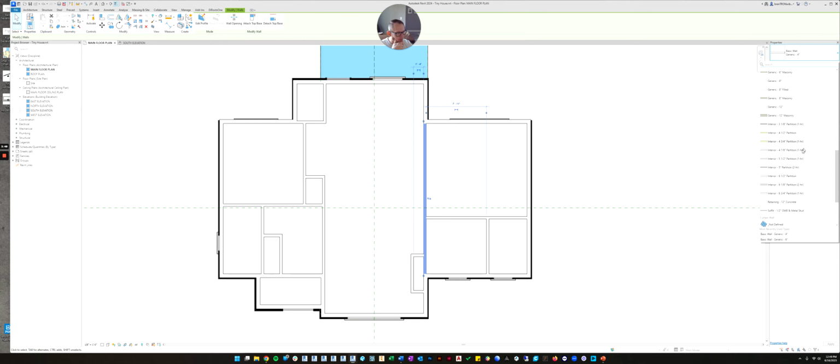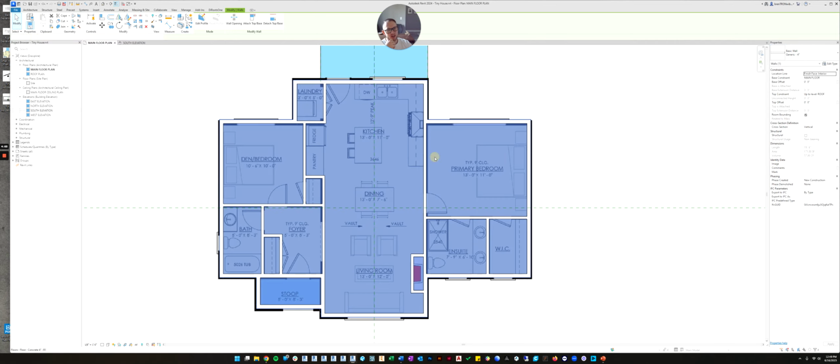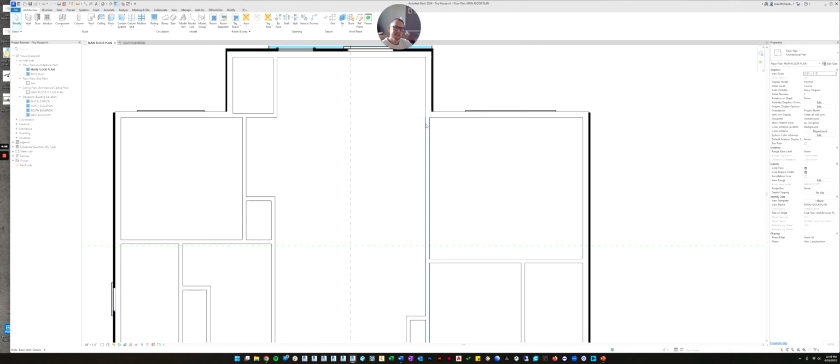Well, I actually do see one that will probably be pretty close. It's this 4.5-inch partition wall is probably what we're going to end up recreating. But I want to recreate it with you so that you understand how to do it. So we're going to start on a wall that's similar to what we want to create. A 4-inch wall is close to what an actual wall will be. So in your mind, before we start editing the wall, let's talk about what the wall should be. In residential construction, the typical interior wall that's not load-bearing is a layer of 2x4 studs, which you've seen in wall framing, and then they put sheetrock on either side.